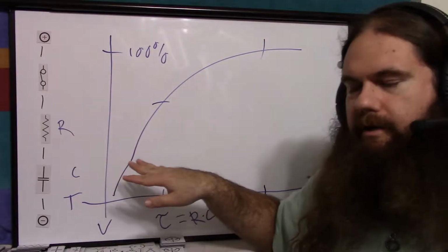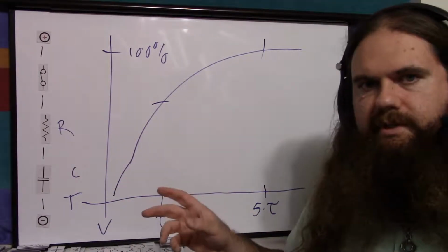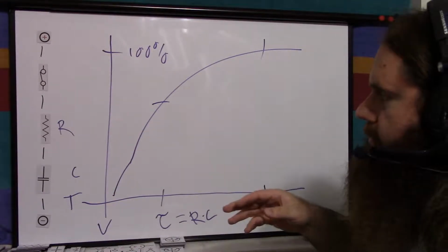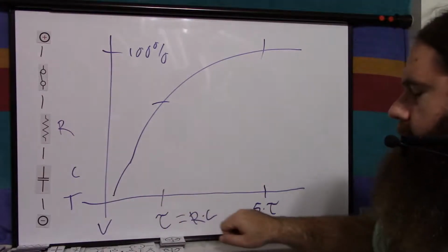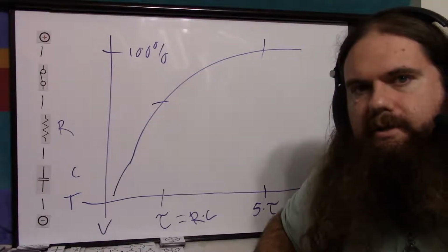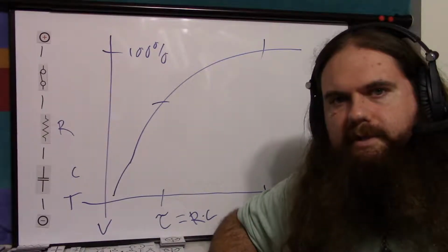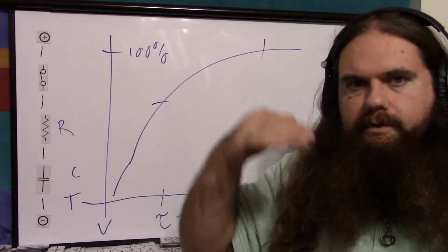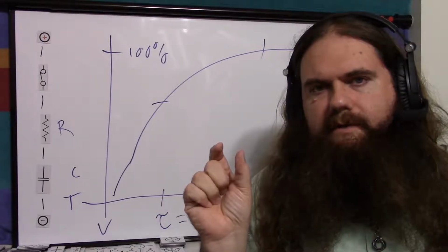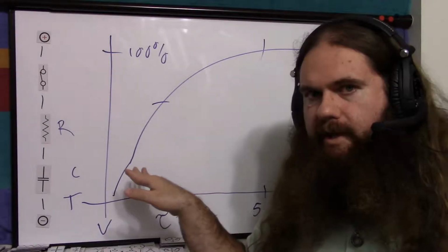So this is the magic of an RC network. You have whatever your resistance is, whatever your capacitance is, and if you have multiple resistors and capacitors, you can just combine them with series and parallel functions until you get down to just one resistor and one capacitor. Multiply them, you get seconds. Multiply them by 5, and that's how long roughly it's going to take to charge your capacitor or discharge your capacitor after you've charged it. And this is used to decide frequencies of things, like if you're applying a square wave, 5 volts, 0 volts, 5 volts, 0 volts, to charge and discharge a capacitor, you know what the frequency of that square wave should be if you want it to fully charge and discharge, or partially, or whatever. That's why we have this.